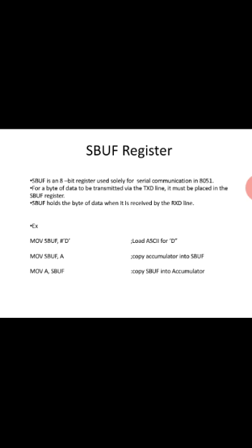And next, the SBUF register. What is this SBUF register? It's a very important register for serial communication. Whatever data you want to send will be put into SBUF first, and then it is transmitted bit by bit. Similarly, whatever data you receive from the serial communication line will be present in SBUF. Later you will copy it into the required registers.